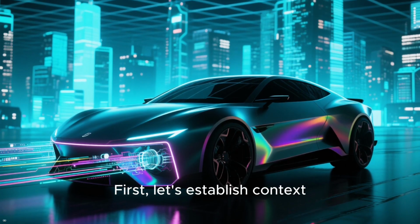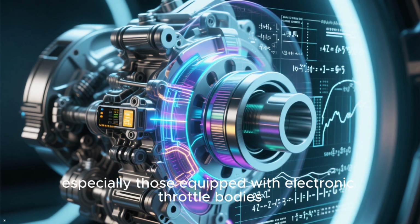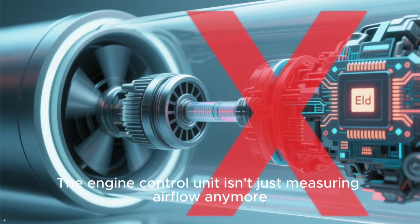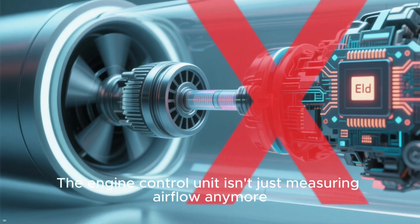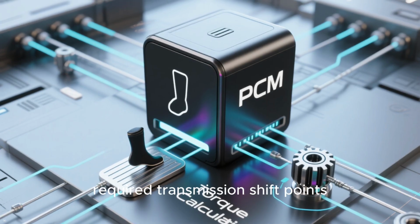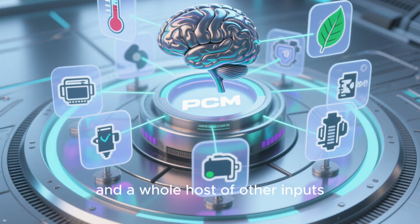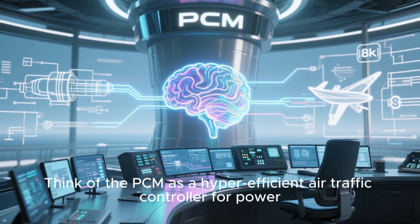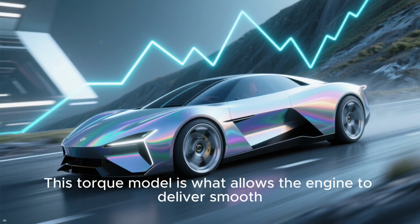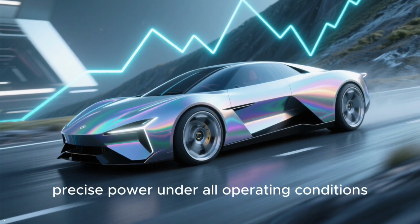First, let's establish context. In modern engines, especially those equipped with electronic throttle bodies, sophisticated torque modeling is absolutely essential. The engine control unit isn't just measuring airflow anymore. It's calculating the precise torque output based on driver demand, required transmission shift points, emissions controls, and a whole host of other inputs. Think of the PCM as a hyper-efficient air traffic controller for power. This torque model is what allows the engine to deliver smooth, precise power under all operating conditions.